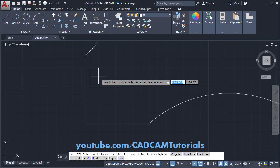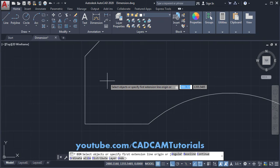You can directly select the object, or you can specify first extension line origin. But to use this command more effectively, using select object is recommended, because by using the option to specify first extension line origin will only create horizontal, vertical or aligned dimension and will not create other type of dimensions.